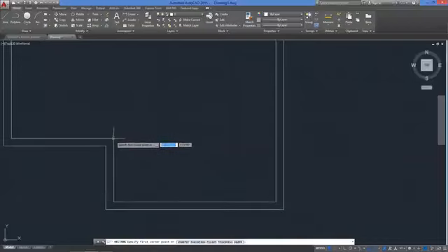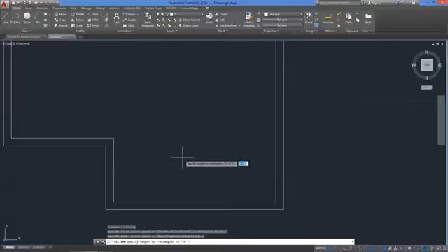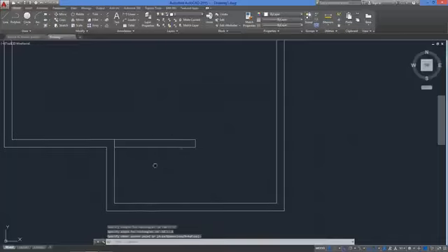First, we'll enter the initial point on the screen, and then it requests the second point, which in a case like this we don't have. So we'll use the option dimension to specify the size. Now, for the length request, we'll enter 7 feet and hit enter. Remember to enter the feet symbol. And for the width, just use 8 and hit enter. Now the final prompt is for the position of the rectangle, and just click on the screen, moving your crosshair or mouse towards the inside to accept the correct position.